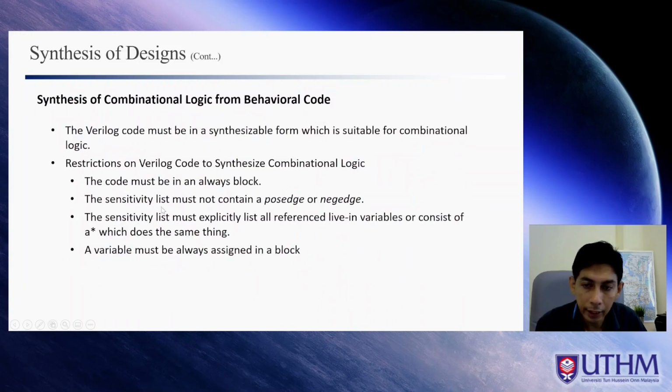The sensitivity list must not contain posedge and negedge. These two we will learn in chapter 4 when we design sequential circuits later on to create the clock.